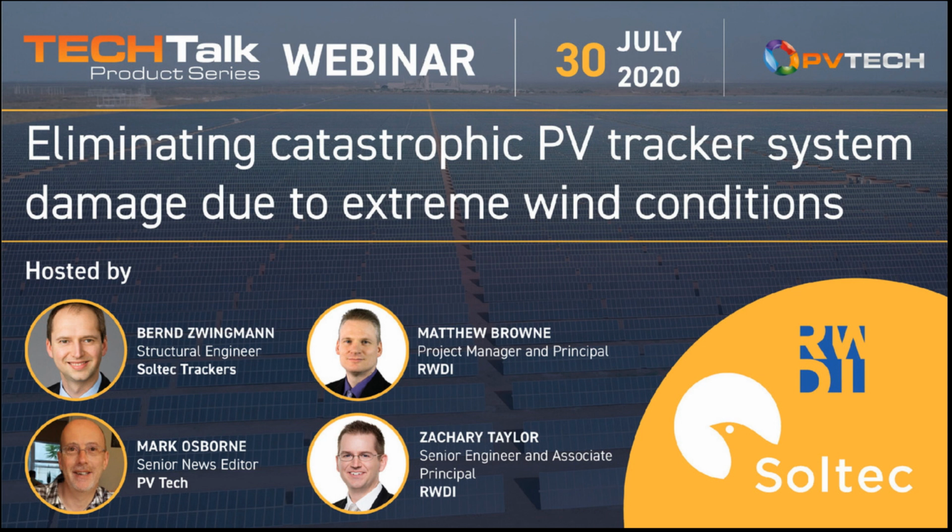You can do it by using several drives, for example. There are such solutions in the market. The Soltech tracker has one single drive in the middle, the one that is usually used, the SF7 system. And this tracker has a stow position for high tilt angle. I think I also said it in the conclusion. So it depends a bit on the site and so on, but it's typically between 45 and 55 degrees that we choose as a stow angle.